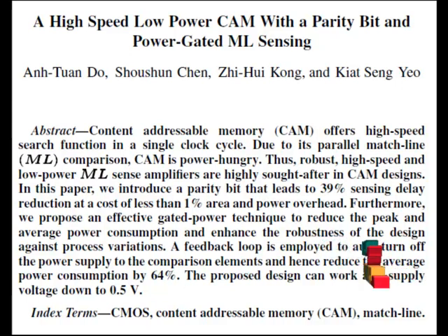For example, consider a CAM consisting of 4 words, with each word containing 3 bits arranged horizontally. There is a match line corresponding to each word feeding into a match line sensing amplifier, and there is a differential search line pair corresponding to each bit of the search word. A CAM search operation begins with loading the search data into the search data register, followed by pre-charging all match lines high, putting them all temporarily in the match state.